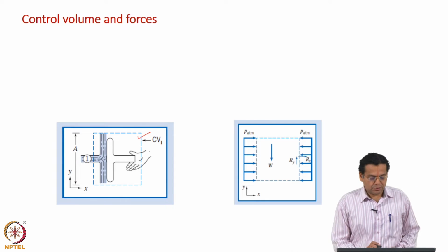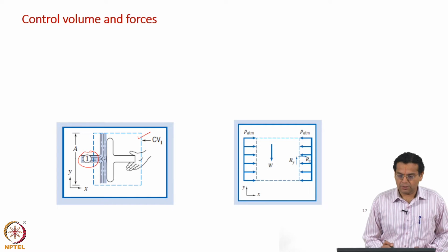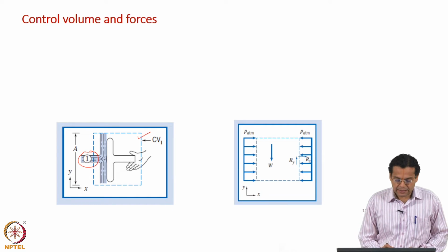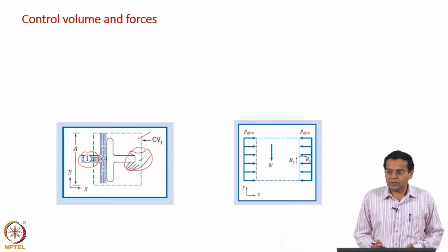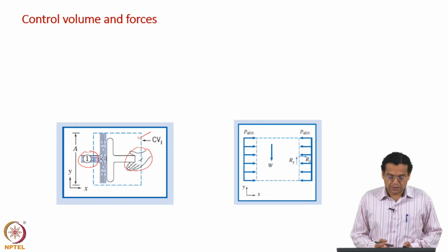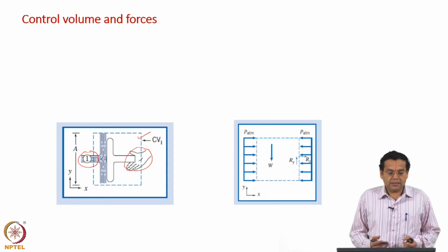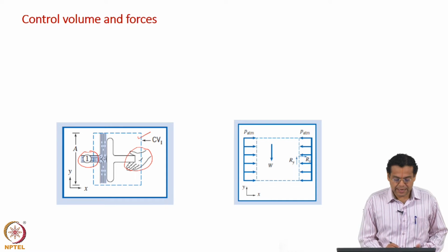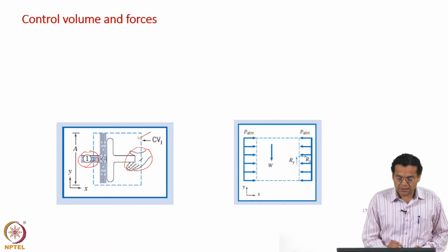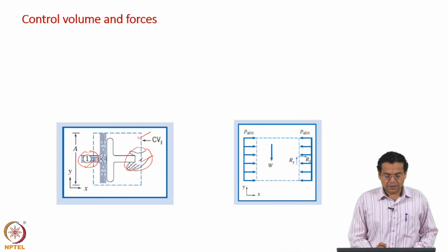When you look at the control volume, there is a momentum flow which crosses the control volume, and then there is a force of our hand on the control volume which is also included, which acts on the part of the control surface. So, when you choose a control volume, you should make sure that whatever we are interested in acts or crosses the control volume or control surface. In this case, this flow crosses the control surface and this force acts on the control surface.